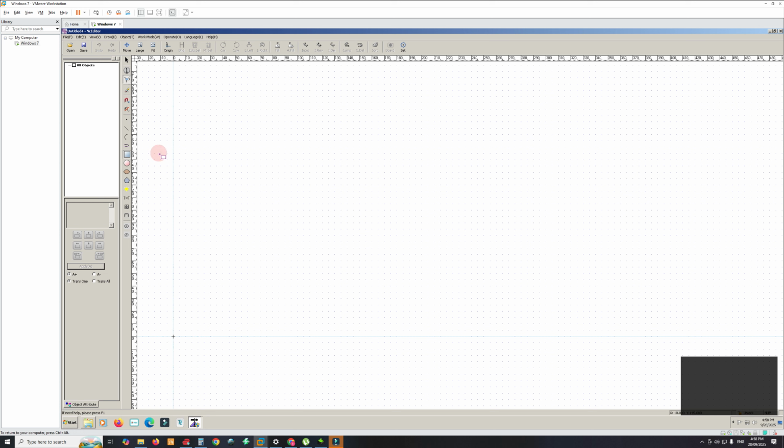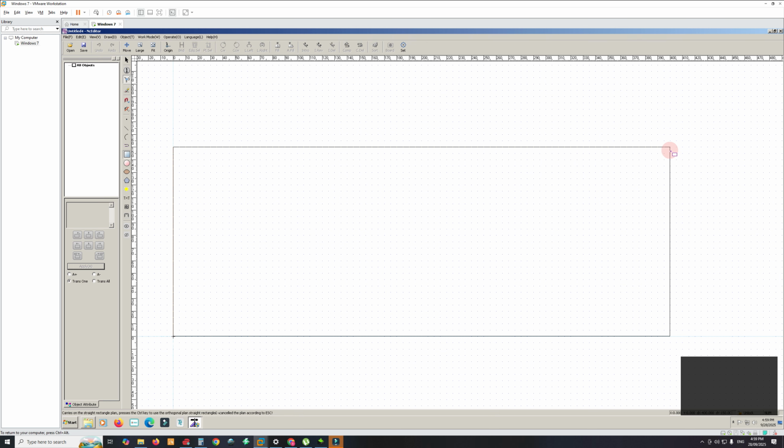It's very important. So to start a basic benchtop, it's just parallel edges, no miters, no nothing, just a rectangle. We're going to go to our draw a rectangle tool. Just left click on the mouse button once to select it, and then you can see it's selected. I've got that little rectangle next to my cursor. I'll go to 0. I will start by clicking it once with my left mouse button. That starts the beginning of the rectangle. I only clicked it once, and now I'm dragging that rectangle out to wherever. Doesn't really matter where, because we're going to do this all by dimensions. And I left click again on that mouse button to complete the rectangle.